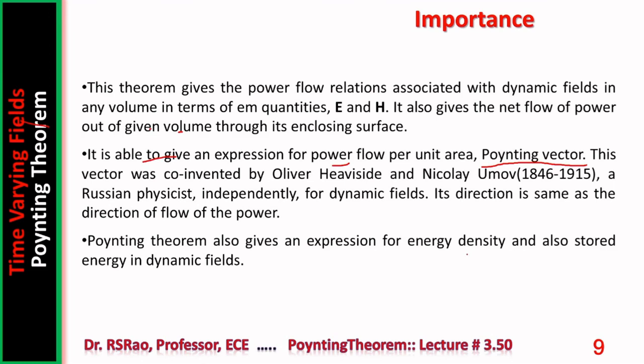Poynting theorem also gives an expression for energy density and stored energy in dynamic fields. So two points are to be noted as far as the Poynting theorem is concerned. First, the Poynting theorem gives an expression for the power flow that exists in dynamic fields. Second, the Poynting theorem is also able to give an expression for the energy stored in dynamic fields. Of course, these energy storage expressions are found to be similar to the energy stored expressions derived while we were discussing static fields.